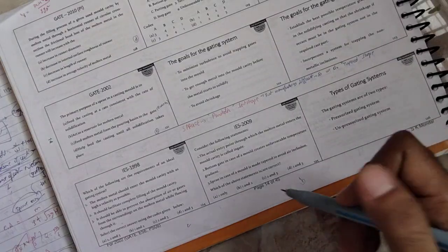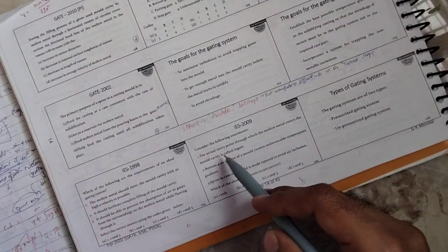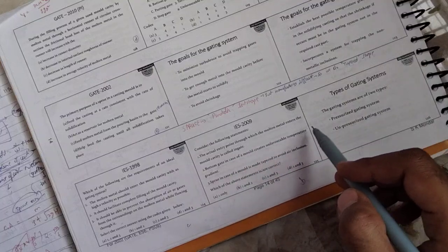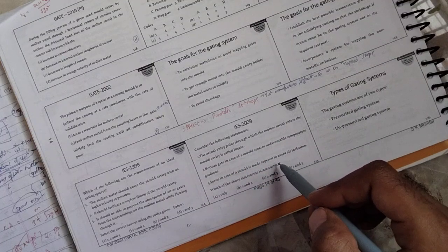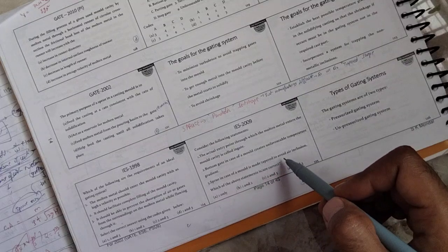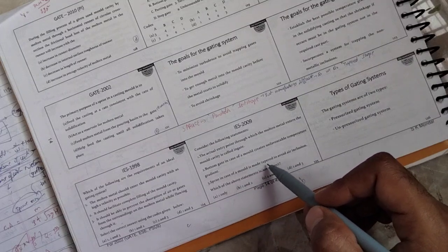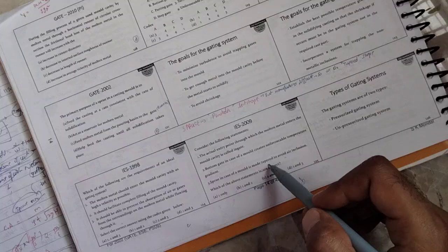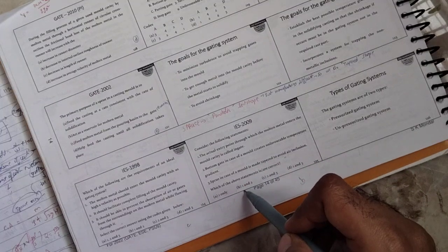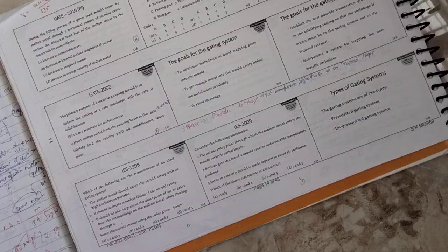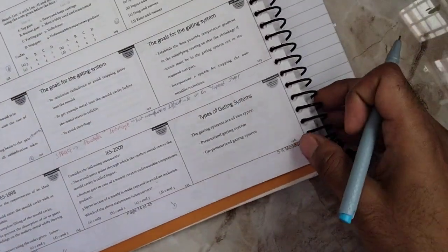Bottom gate is unfavorable, as referenced. Sprue is made tapered to avoid air inclusion. So it's made tapered to avoid that. So option 1 and 2 is the right answer. Okay, we can just go to the next question.